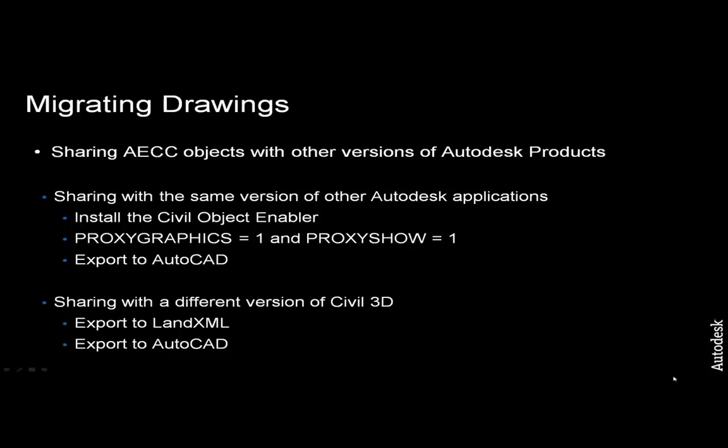If you're looking to share your drawing with a different version of Civil 3D, your options are limited. If you need that Civil 3D to retain its object intelligence, you're going to need to use the Export to LandXML command. Most civil objects can be exported to LandXML and imported into a new drawing of the new format.